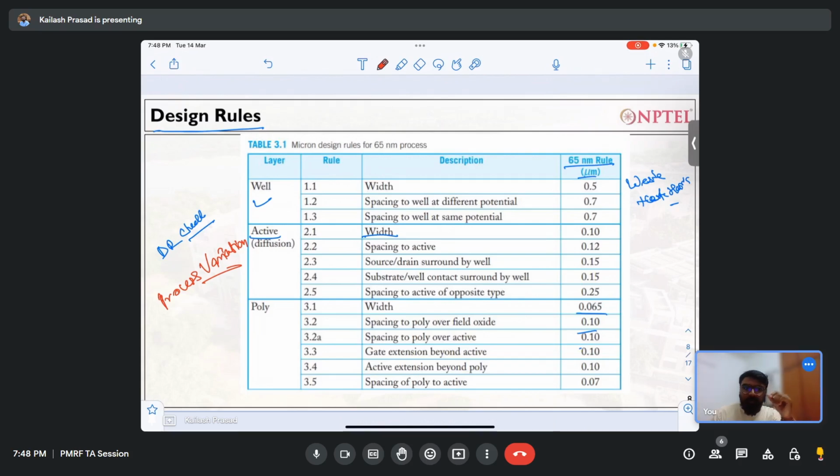Okay, so if you have any hands-on experience designing any digital or analog circuits, there is one step where, if you want to say that my circuit is working extremely correctly, there are actually three tests you have to do to make sure that whatever circuit you are making will be working in all conditions. And these three tests are called PVT. You should note down all of this, because these are very important points as a VLSI designer. And the first is what we call process variation.